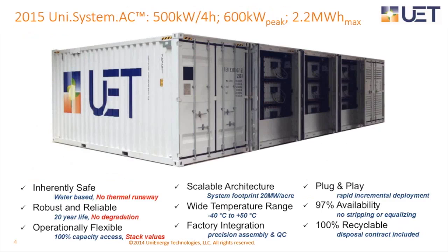Let's go to the next slide, and I'll focus on the product and how it's used, not so much on the chemistry, with the prior presentations covering that well. So what do we make? We take all the attributes of our advanced vanadium flow battery, and we have a product based on a modular system comprised of 4 20-foot containers with the batteries coupled to one inverter container that has a PCS and an isolation and step-up transformer, with a nominal rating of 500 kilowatt, 2 megawatt hour.